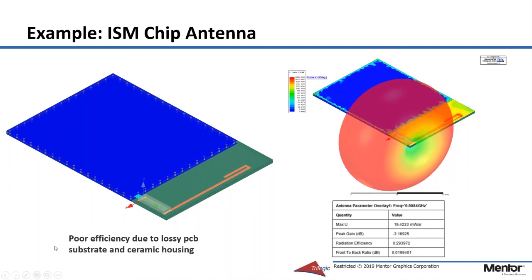Well, here we have a rendering from PADS, and here is the imported file from PADS in ANSYS HFSS, and it's showing a dynamic animation of a far field on the bottom here, and currents and voltages here on the actual PCB. The chip antenna, which was placed in PADS in 3D, was imported, and you can see it right here.